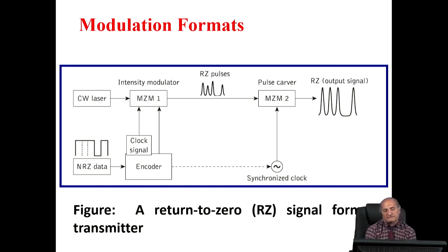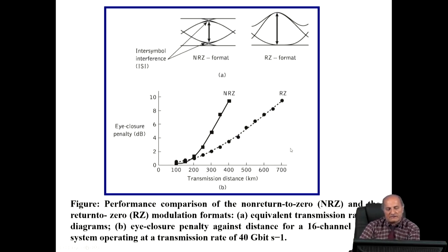If we look at this figure, we use two Mach-Zehnder modulators, one to generate the pulses, but the top is not constant. And the other Mach-Zehnder modulator equalizes this amplitude variation and generates digital optical pulses with constant amplitude in logic 1, because in logic 0 the power is low.